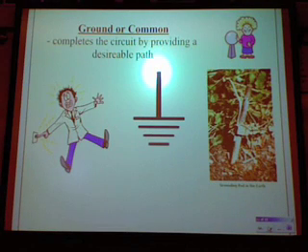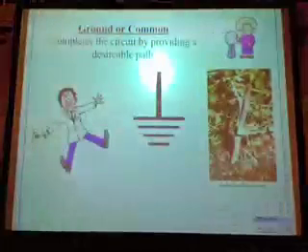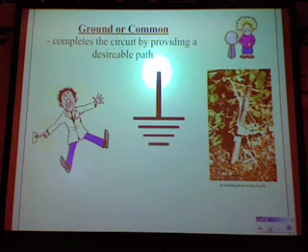You guys know where your breaker box is at your house? Where you can turn off electricity? You should all know that. Just like you should all have a fire plan if your house catches fire. You should know where the breaker box is. So if somebody's getting electrocuted, you can run out there and flip off the big switch and save their life. Well, right by that breaker box, if you look down around the ground, you might see a wire coming out of the house or even out of the ground, and it might be a bare wire clamped on to like your metal water pipe that goes into the ground. That's the ground connection for your house.